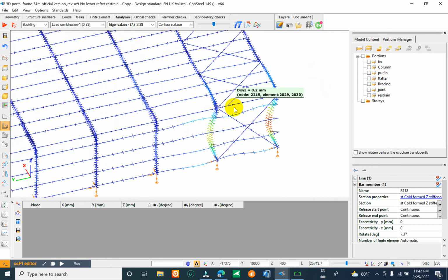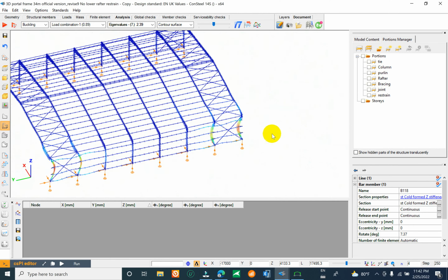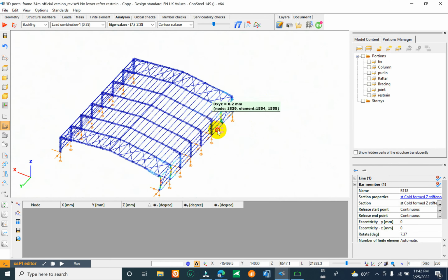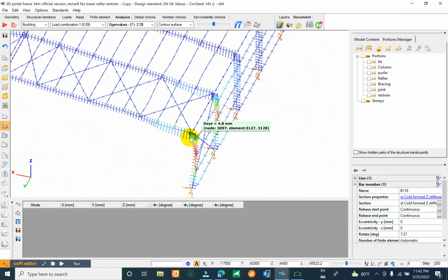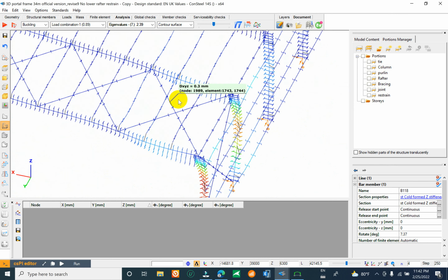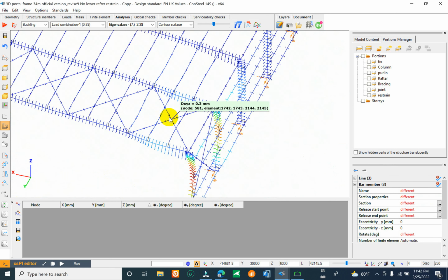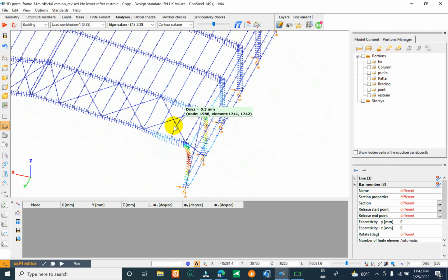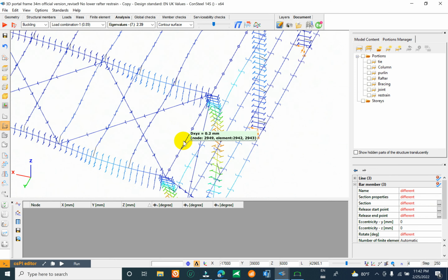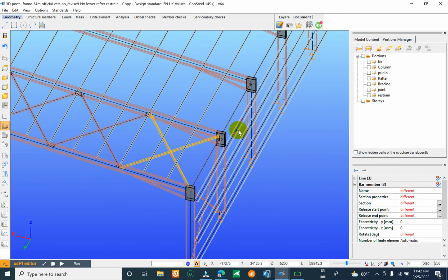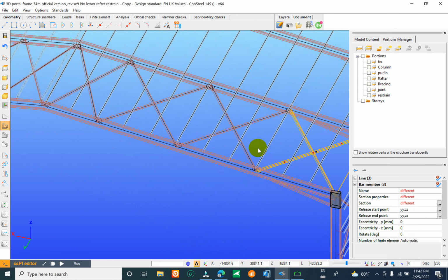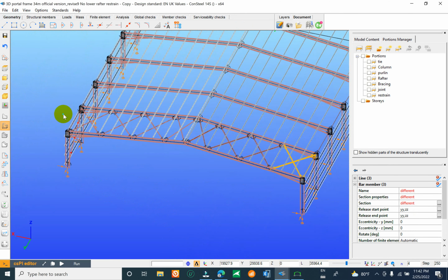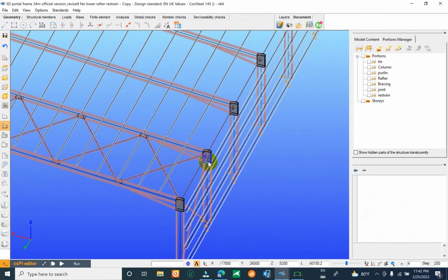You can see here this one also, okay. So you know the bracing is very important. When you add the bracing here, you make sure you have stability in out of plane, and together with this one and this one is very important, okay, to keep out of plane or the whole frame, okay, stable.